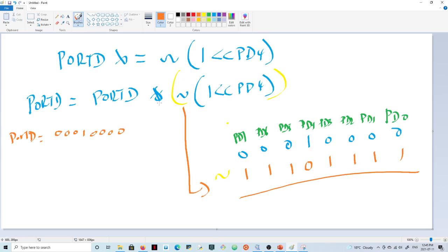So now when I AND it here with 1, 1, 1, 0, 1, 1, 1, 1, what am I doing? I'm concerned with pin PD4. So PD4 is this guy here.